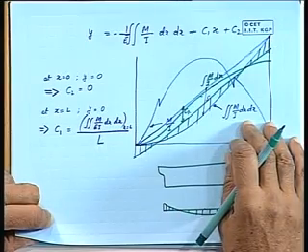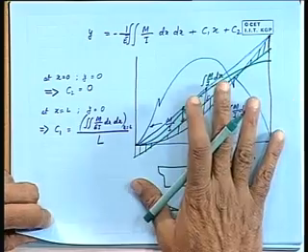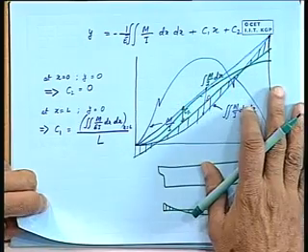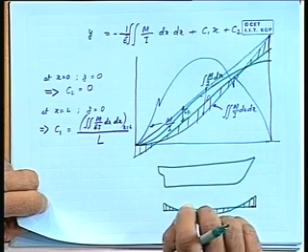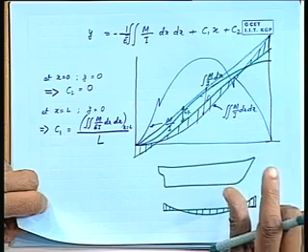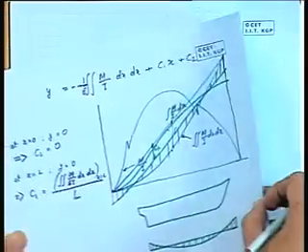Okay? Now, many a times this is a debatable thing, that whether the neutral axis is going to be at the mean level. No, it is not. It only gives you a representation. It is not the exact value, and therefore, you will find that the displacements are seldom given in absolute manner. Rather, it is given as a fraction of maximum displacement. So, wherever the maximum displacement is there, remaining displacements are given in terms of fraction of that maximum.